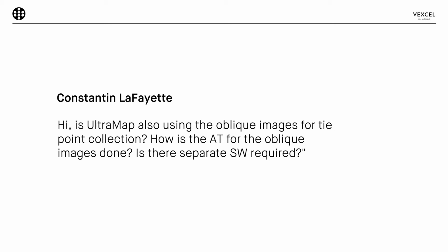Or then we have one option which means a little bit reduced processing time, that is using all nadir images and just a subset of the oblique images to get a faster solution. So there is no separate software required for handling the oblique images. Full handling of all oblique data in the post-processing step, aerial triangulation, radiometric adjustment, and so on, is fully integrated in the UltraMap software.